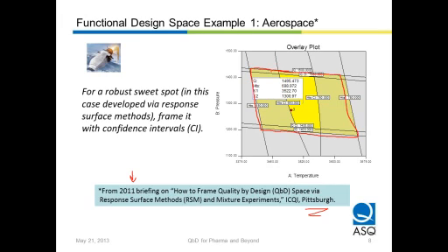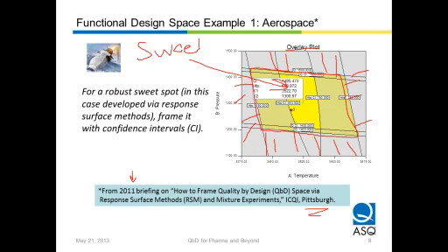But again, what we have here is a region, which I'm drawing out here with my red marker, that is the sweet spot. Okay, so this area here is sometimes called an overlay plot, where we've shaded out any results, and there's two different responses here that don't meet specifications. So all of the parts outside of this red box that I'm drawing lines out from, this area on the outside of this region does not meet requirements for the unit operation. Okay, so here then in the middle is what I would refer to as a sweet spot. As long as we stay inside the sweet spot, the process will meet requirements and we can continue on to the next unit operation.